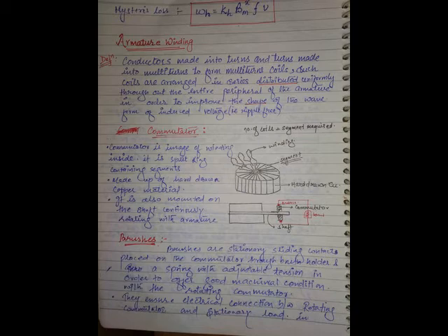Is it clear? Similarly, take another bunch, strap them, tie them together. You have a bunch, you place in one more slot. Is the point clear or not? Two slots are enough now. If you place all the conductors in such a manner, it is concentrated winding.